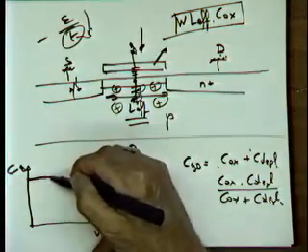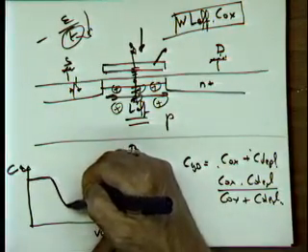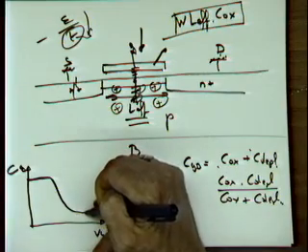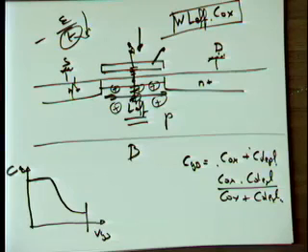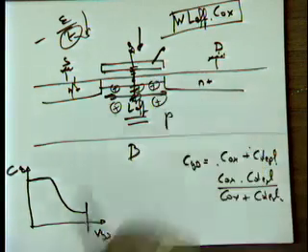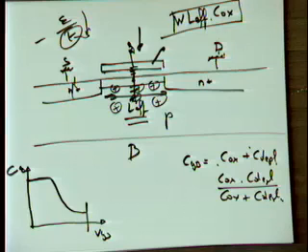So initially this is constant, and then we will see my capacitance starting to drop. That's why you have this dip. A depletion capacitance forms. And then suddenly, click, the voltage at the surface is going to go to 2 phi F, which is the Fermi voltage.